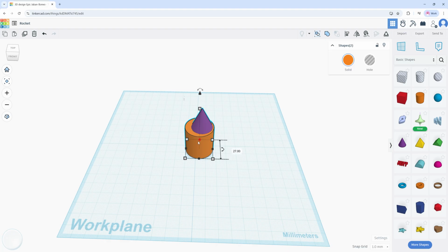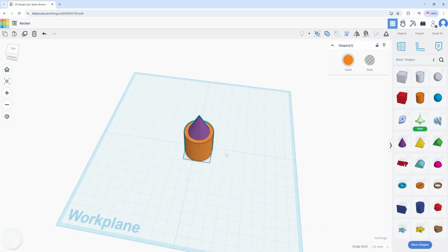Press L or click on the Align toolbar. The hotkey for that is L. Click the center dot to align along the x-axis. See, all the center dots are aligned. Now they are perfectly centered, much faster than eyeballing it.